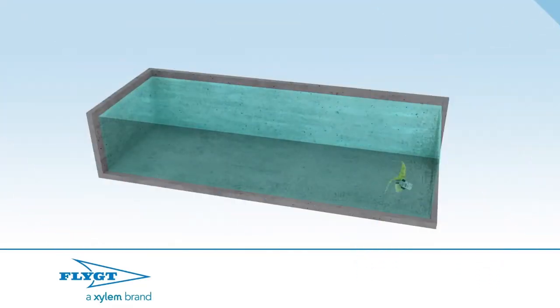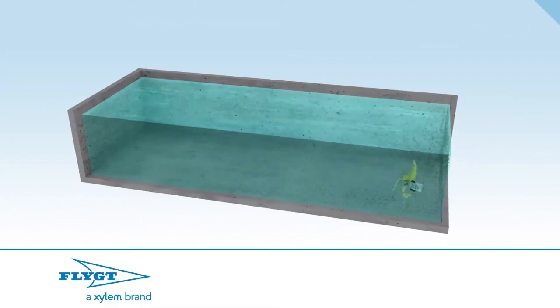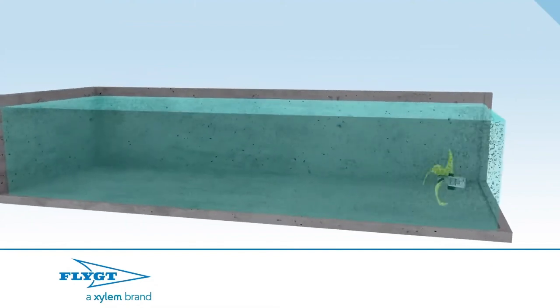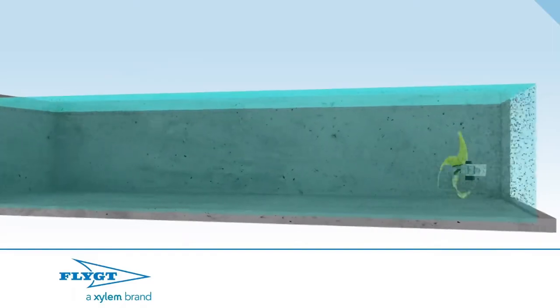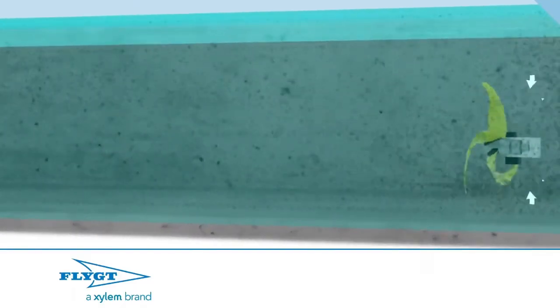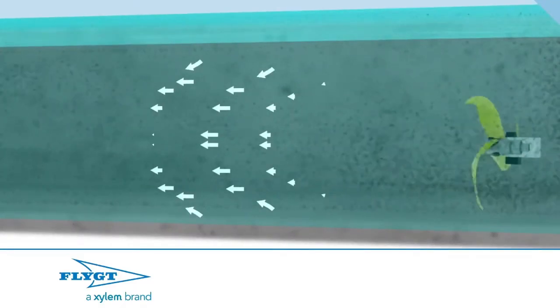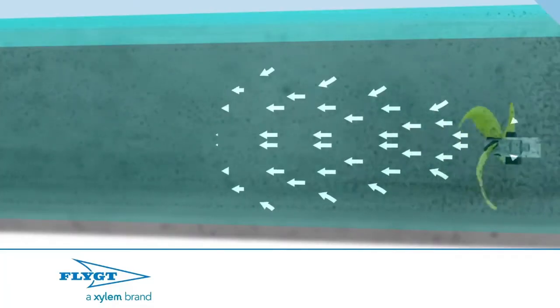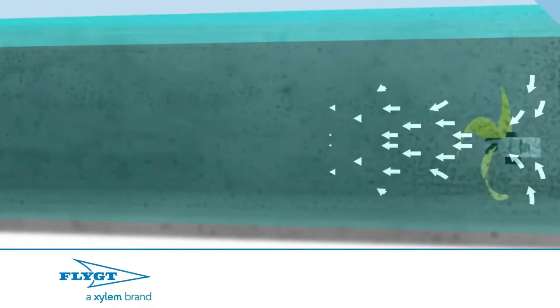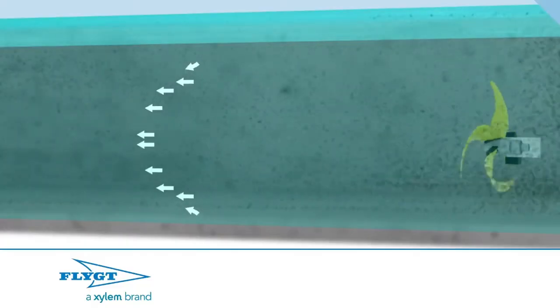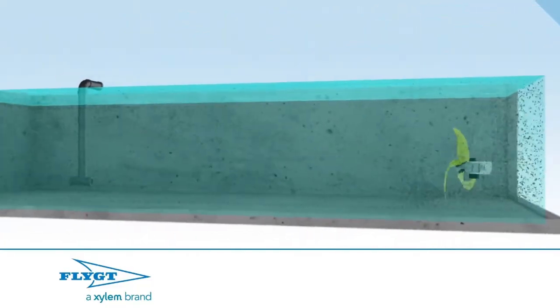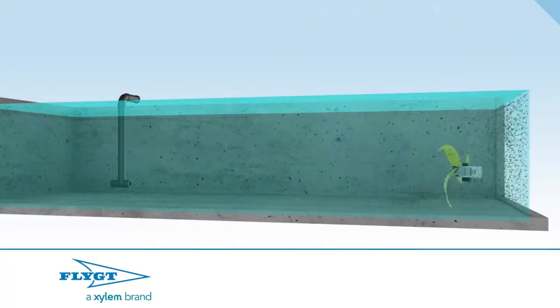In addition to bulk flow, an intense amount of mixing is happening around the jet boundary. As the jet expands, it entrains more of the surrounding fluid. The jet gets wider and slower until it is moving the entire contents of the tank along with it, achieving an efficient bulk flow for effective mixing. Over the years, leading manufacturers like Flygt have developed advanced models for predicting the amount and placement of thrust required to achieve proper mixing for a wide range of mixing duties and applications within typical tanks.